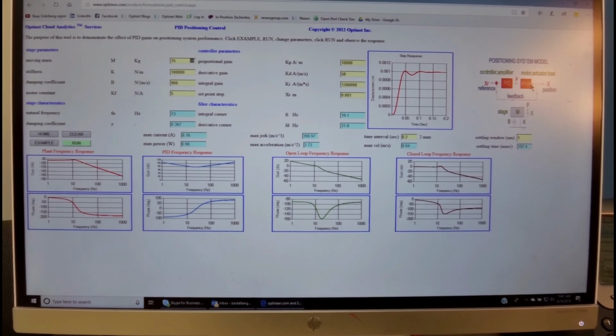In other words, if we just take the plant and apply a force over here and observe the displacement, and we change the frequency of the force, we'll get a curve like this. We measure it in logarithmic scale by dB, and dB is 20 times the log of the output divided by the input, which is the basic gain.